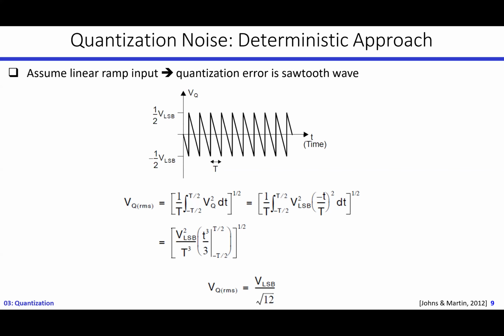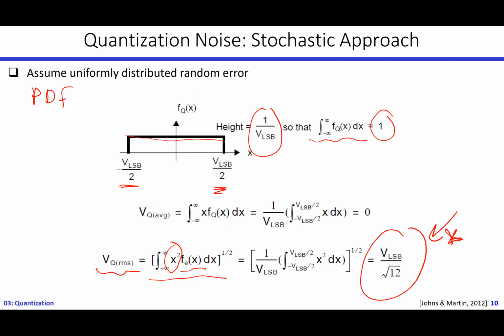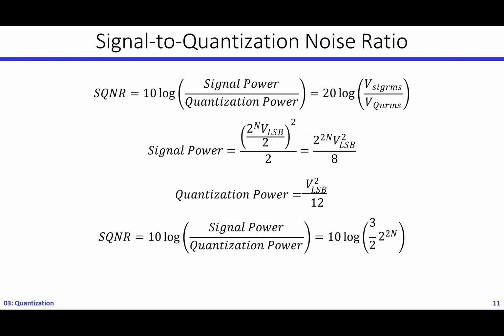So we don't need a very low resolution ADC. We usually need 10 to 14 bits in many applications. If you need a higher resolution, you will even go to 20 or more bits. The lower resolutions are not of very high demand application-wise, so we are focusing on the larger numbers.